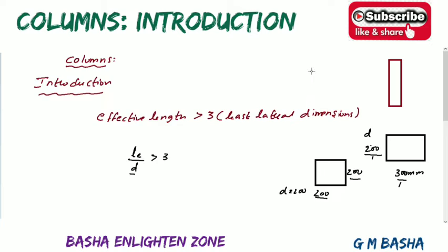There will be circular columns also. For circular columns there will be only a diameter, like some 300 mm. At that time you can consider just whatever diameter is given for that circular column. So if you observe, the effective length to its least lateral dimension is greater than 3. Whatever effective length is given, divide it by the least lateral dimension. For example, for a square one you can take 200, and for a rectangular one, out of these two whichever is less, that is 200, that is the least lateral dimension. For a circular one you can take directly 300. If you take that ratio and it is greater than 3, that comes under the column.